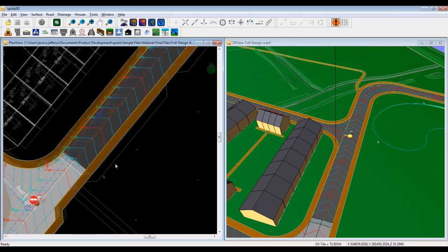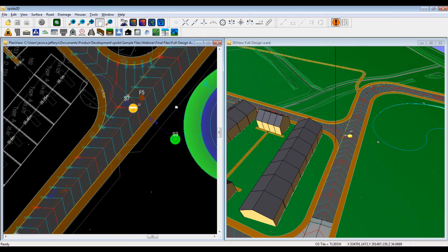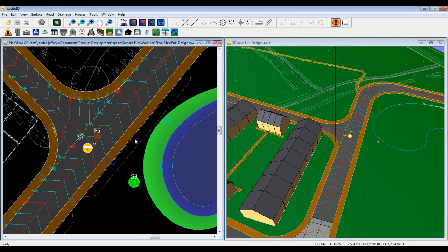There might be any number of reasons why we don't want that to be the case. Drainage is obviously a key reason. So we'll add this road widening, which might be, say, a parking lay-by, and we'll make that have a different grading from the existing road channel, just to show you how that works. So our first road widening we designed with the channel tools. So we were able to add a parallel option, a road widening, miters for where we have wider corners, but we're going to use the secondary channel tools.